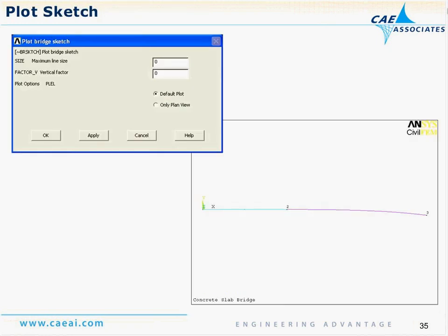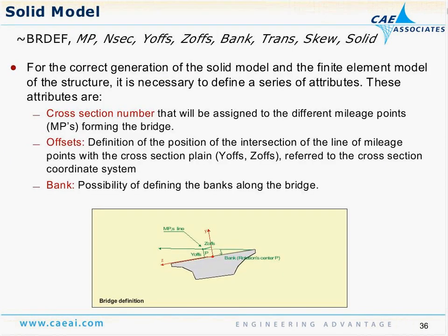And it's just showing that once you define some of your entities, you can go ahead and plot the sketches. You can also assign the predefined cross-sections at particular locations along the length of the span. It'll automatically extrude between cross-sections to get you a continuous mesh. And again, this mesh can be either beams, shells, or 3D solids.